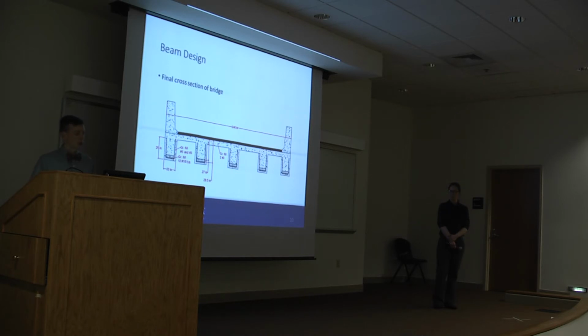We had to check against deflections, but AASHTO doesn't define any deflection requirements as long as the driver feels safe while going across. But we added the ACI deflection code, which we met.